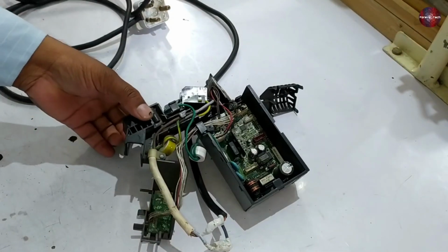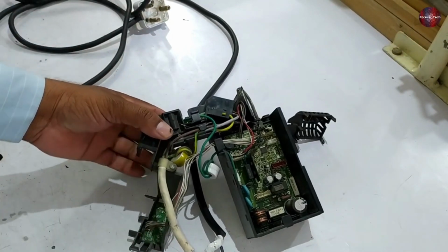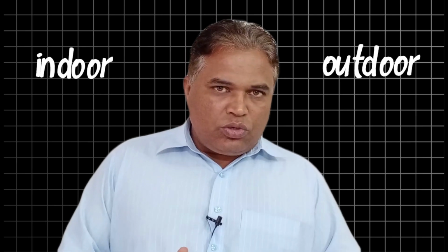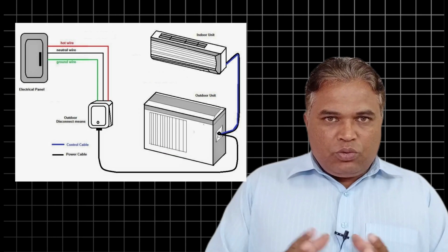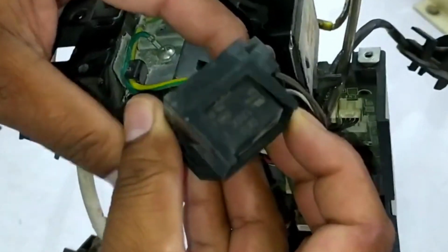We have now opened an indoor unit PCB, and this circuit board is in front of us. However, before proceeding with troubleshooting, the first step is to determine whether the fault is in the indoor unit or the outdoor unit. Since this is a 1-ton unit, its power supply flows from the indoor unit to the outdoor unit. Now, let's examine the relay on this PCB. I will show you exactly where the relay is located and also open it up to give you a clear view of how it looks.